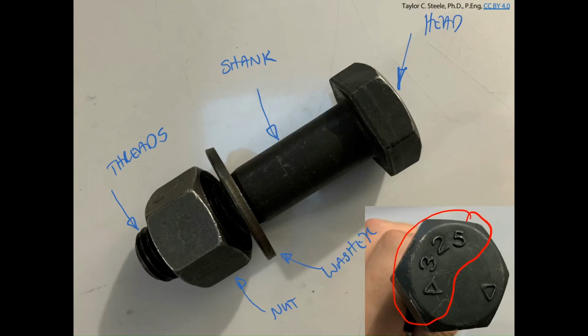The last one I'm going to pass around here is a little bit interesting. It does not have a hex head. In fact, it doesn't have much hex at all. This is called a tension control bolt, and basically what happens is you don't do anything with the head at all. You put it in place, and then you have a torque gun at the back that's used to grab onto this little piece of steel here at the back. The gun holds into that and spins the bolt. Once the bolt is adequately tensioned and there's an acceptable amount of torque on the nut, they're going to shear that little piece off, and that's going to control the amount of torque that gets applied to that particular bolt. We'll pass another one around in a minute, but we'll wait a little bit later to get into what's different with that bolt.